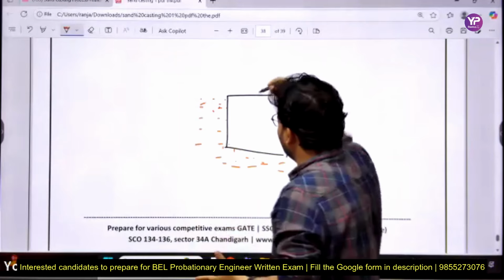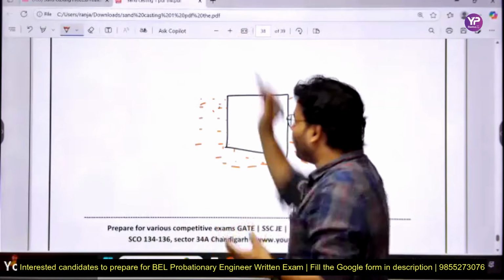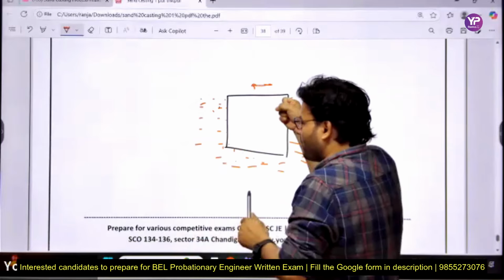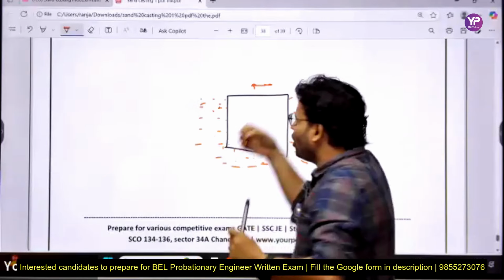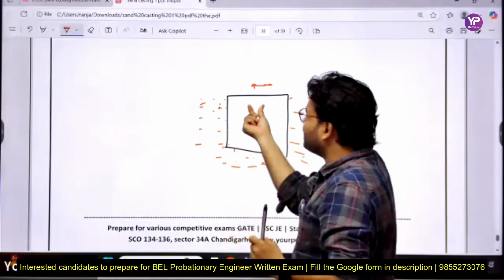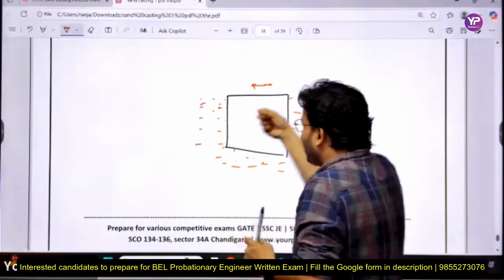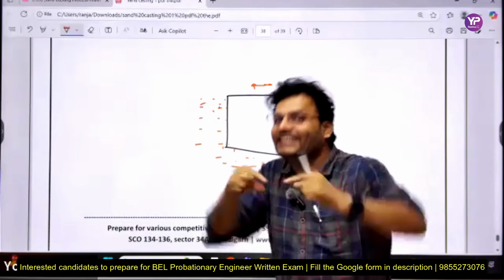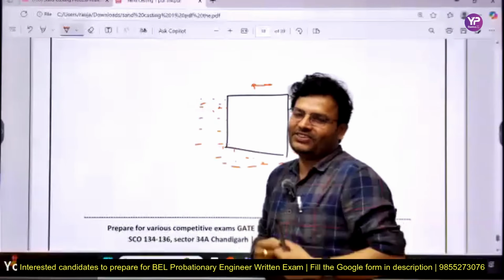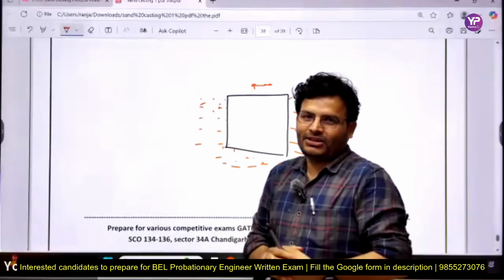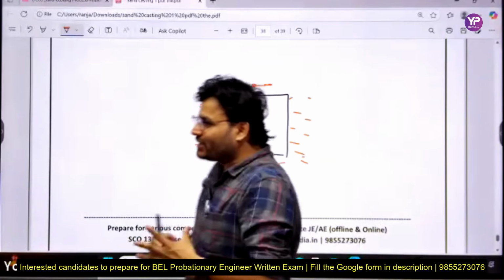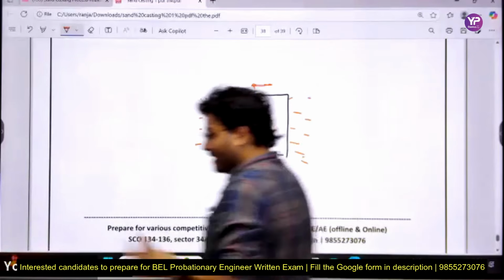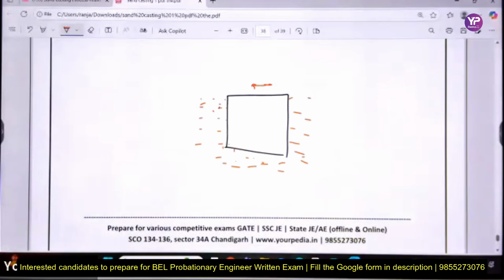Even draft allowance is also there. So before taking out the pattern from the cavity, you will shake it a little bit, left and right, a very little amount. And that's why the size of the cavity increases a little bit, and that type of allowance is known as what, my dear friends? Shaking allowance. So now the question is going to be asked: which type of allowance is shaking allowance? Make a comment, positive allowance or negative allowance?